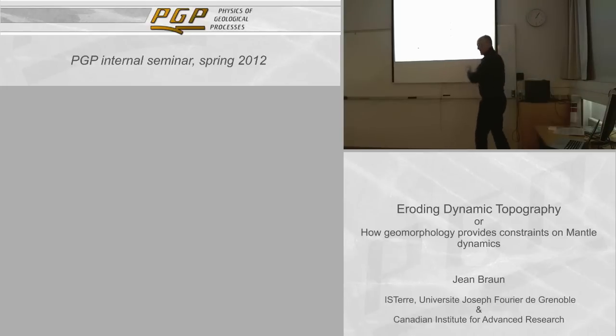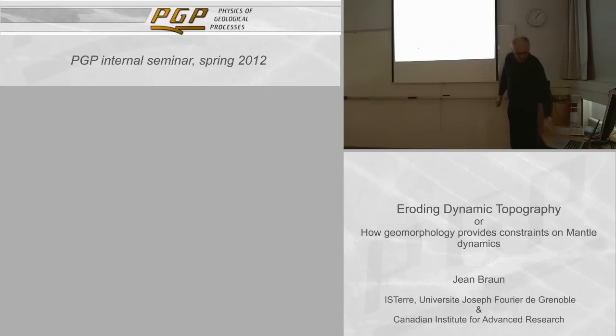I reverse the order again. And I do the same thing as I did with the water, but now I do it with how much erosion I've predicted here. And by doing that, I accumulate down the network the sediment flux. How much I've actually eroded from the landscape and given to the river. Okay? So I have that another component of this that's very important, how much sediment is being routed at every point of the network. Again, I only need n. All these operations are order n, not n log n, they're only n.